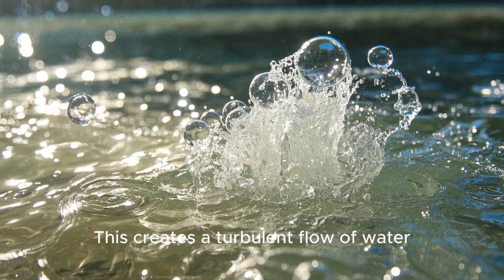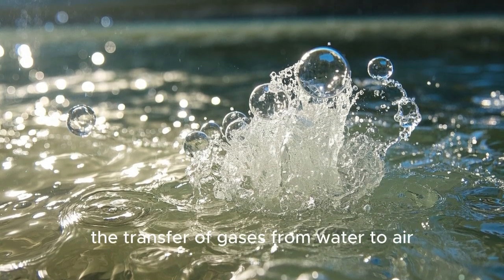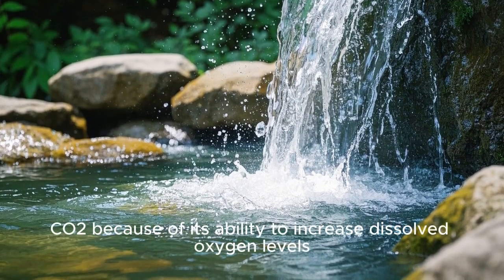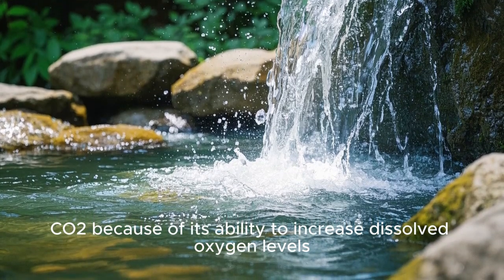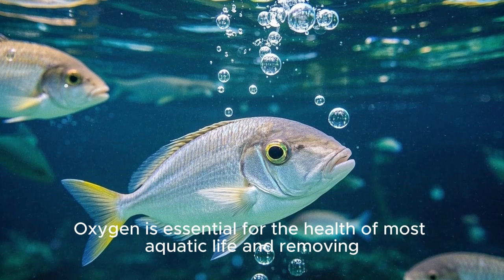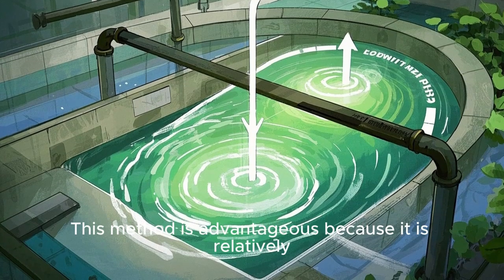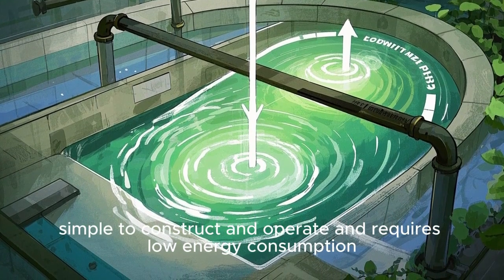This creates a turbulent flow of water, maximizing the water-air interface and facilitating the transfer of gases from water to air. Splash aeration is particularly effective at removing CO2 because of its ability to increase dissolved oxygen levels. Oxygen is essential for the health of most aquatic life, and removing CO2 is important because high levels can be toxic. This method is advantageous because it is relatively simple to construct and operate and requires low energy consumption.